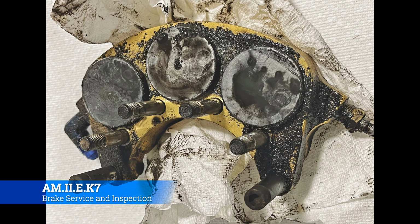You're also looking at, behind every one of those pistons, typically you'll have at least an O-ring, if not an O-ring and then another white pressure ring that goes behind it, just depending on the model of brakes. Those will go bad over time, and you'll have to pull them out and replace them. Not really that big of a deal, not that hard, not that expensive to replace, but just something you have to keep an eye on. So that's something you're also looking for.